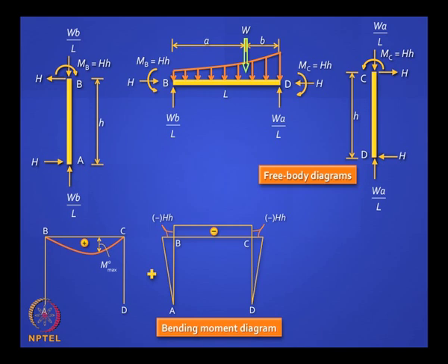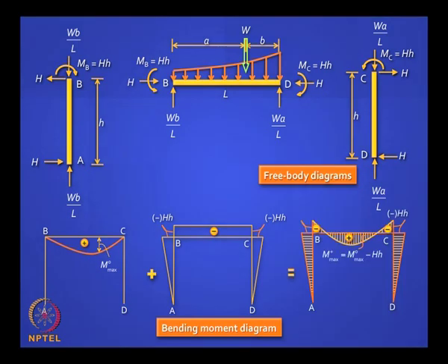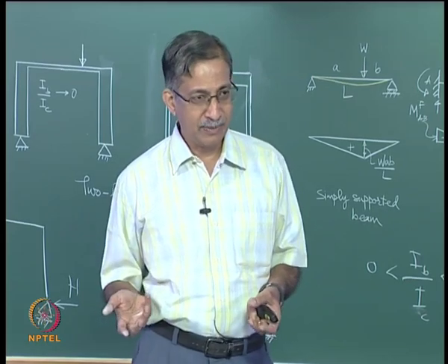It is a linearly varying bending moment, right. So this is your resultant bending moment diagram. Can we write this expression for the column? That is, if you take the column and say starting from the base x pointing upward, is this expression correct? Whether you write plus or minus depends on your convention, but let us say we are sitting inside that frame, so it is outside, so we can treat it as hogging, right.